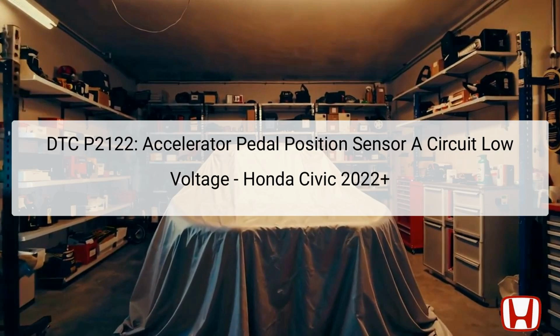The APP sensor's location in the accelerator pedal module means that issues can arise from both mechanical obstructions and electrical failures in the circuit pathways to the PCM. The DTC P2122 indicates that the accelerator pedal position, APP sensor, has output voltage which is insufficient, specifically falling below the PCM's acceptable level. The PCM is the electronic control unit that monitors and adjusts various aspects of engine operation, receiving data from multiple sensors to improve performance and efficiency.